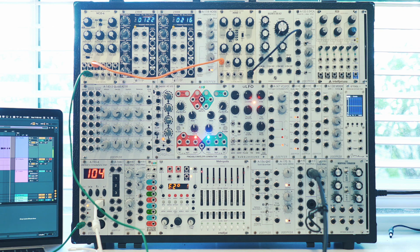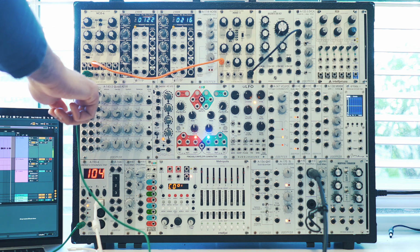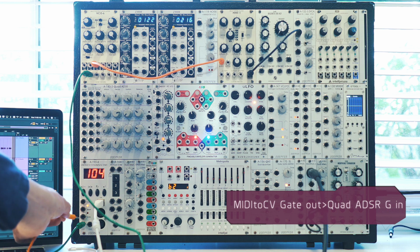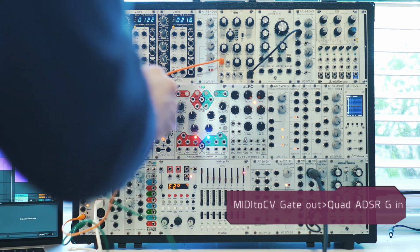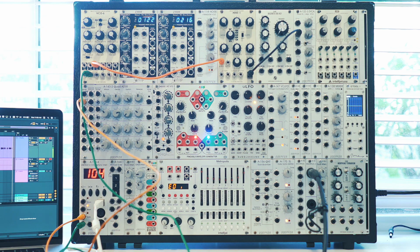So let's take the gate output from our MIDI to CV module and plug that into the gate input on this ADSR here. Now, if I was to just send in some MIDI data, so I'm just playing on the virtual keyboard on this laptop here, we're not hearing anything yet because nothing is connected to the audio output, but you should notice that on the MIDI to CV converter module, as I'm playing different notes, that gate LED is lighting up. So we know that it is working.